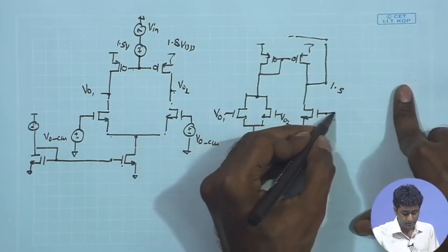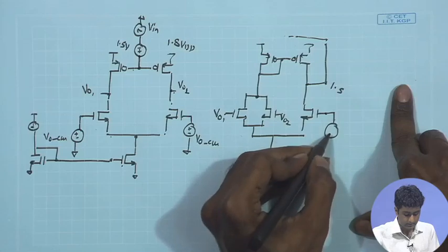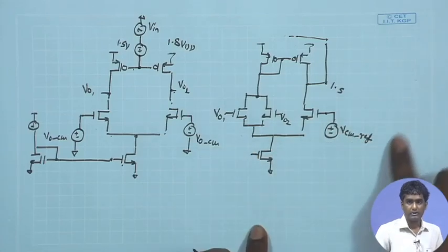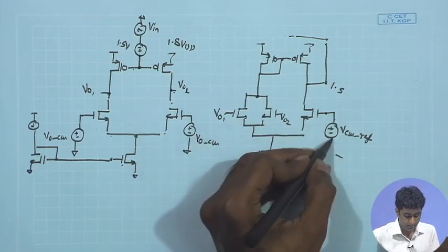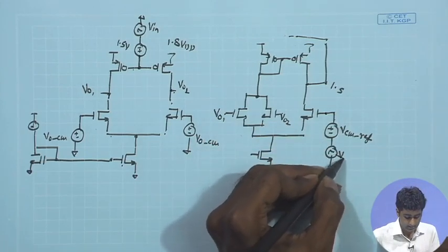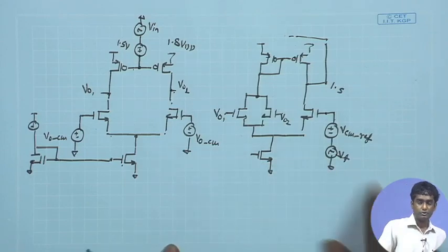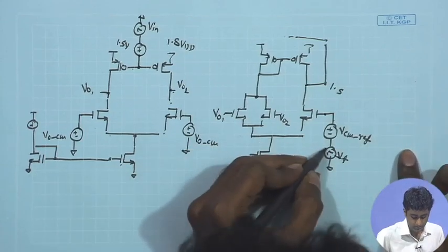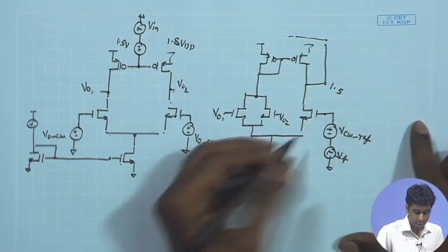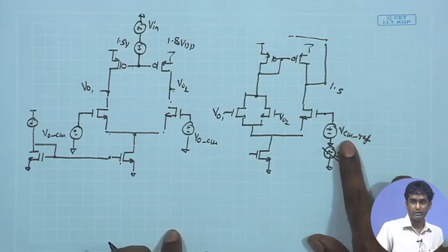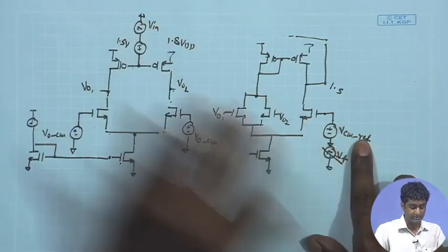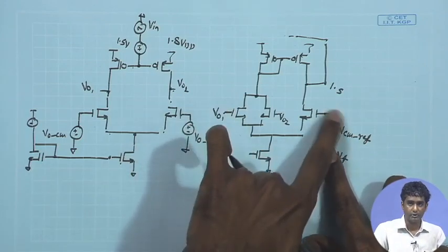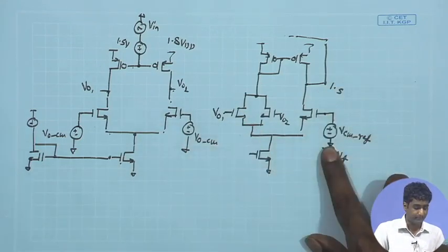And of course, here we also need to keep the same Vref, I would say VCM ref, that we had under the normal closed loop operation, and then apply an AC signal on top of that, Vtest if you call it. Sorry, in this case we are not applying the test signal over here, but we just need to put it at the required VCM, because in this particular first case, I am assuming that the input signal is applied over here. So, you just need to make sure that this is also at the same VCM ref that you had applied.